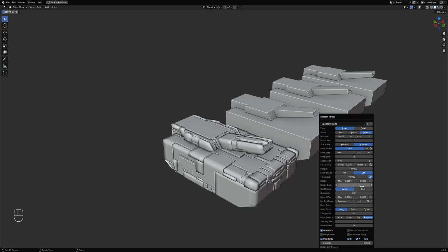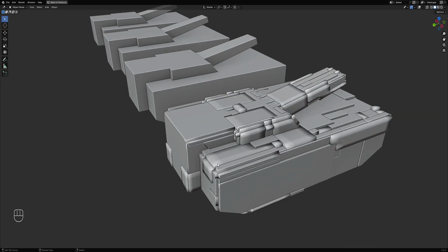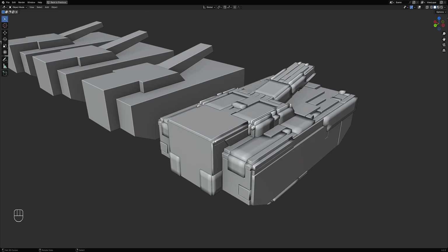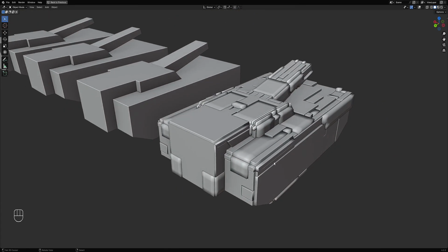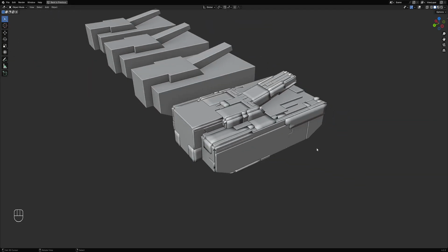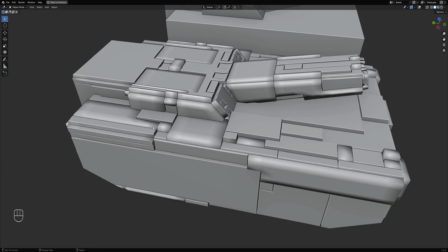There's also another way using the cut method split, but the sharp edges, the transition of the panel islands in the areas of the sharp edges, will be split, compared to using wrap, which of course wraps or continues the panel island on sharp edges.